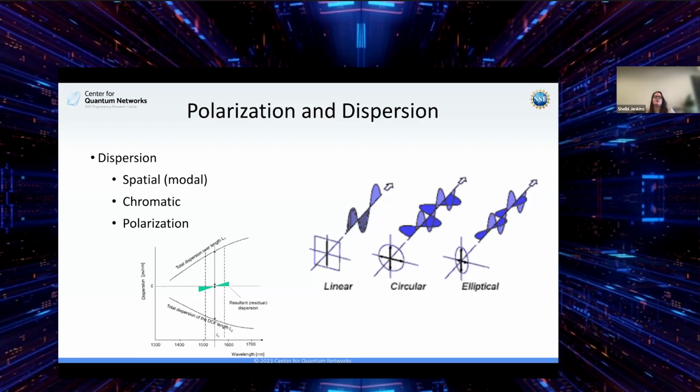So we talked about how, depending on the characteristics of your waveguide, you can support one or more modes. And like I said earlier, when working with long haul networks, having multiple modes within a fiber can degrade the quality of your signal because those modes are going to propagate at different speeds. So when you're working in fiber or any type of waveguide, you're going to want to consider how long of interaction you have with your materials and your devices, and whether or not you're going to need to compensate for these different types of dispersion, so that on the receiving end, of the consumer node of your network, you are getting the signal that you are anticipating.